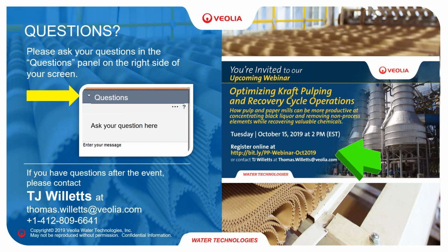So we introduce a calcium removal step, and that is typically done on the effluent of the anaerobic reactor. And then after the removal of calcium, we take the low calcium effluent from that stage, and we bring it back to the inlet in order to dilute the calcium in the inlet. Because calcium carbonate will only precipitate above certain threshold levels. So as long as you stay below the threshold level, you can operate the system, and the calcium carbonate will not precipitate out to the extent that it will cause an issue or a problem.